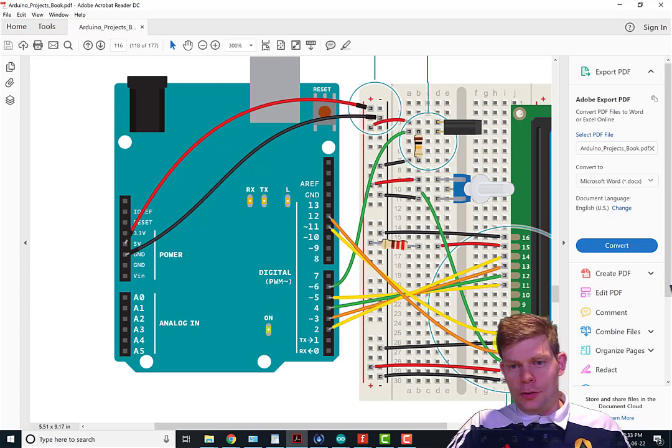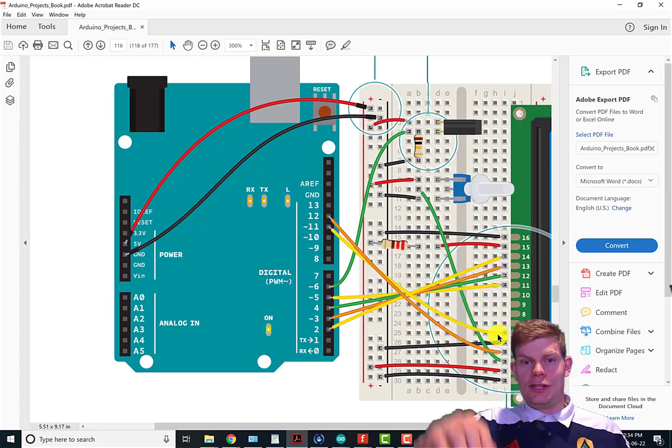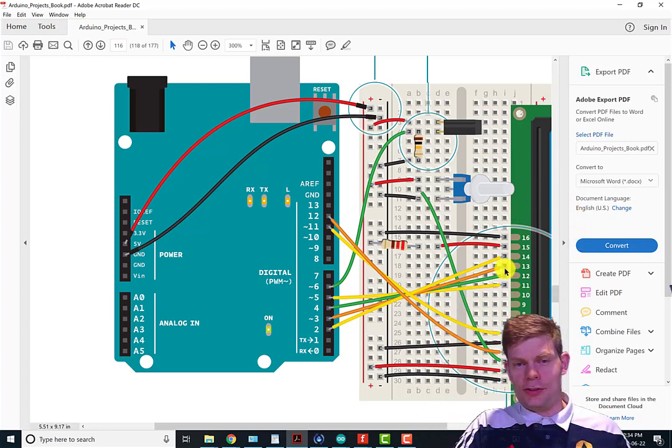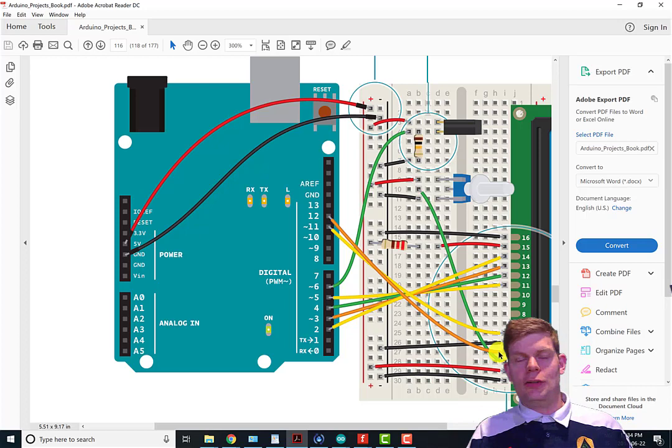With our read-write pin, we only want to write to the LCD, so we just connect that to ground to force it to be in write mode. This guy right here is our enable. Our Arduino is going to handle all that with our liquid crystal object. It's connected to pin 11, and that'll just go from high to low to high again every time it wants the LCD to do something, draw a character, do a command, whatever. And then pin 12 we've got connected to the register select, so that'll just be constantly toggling between instructions or character mode, depending. And then we just got our main power connections.